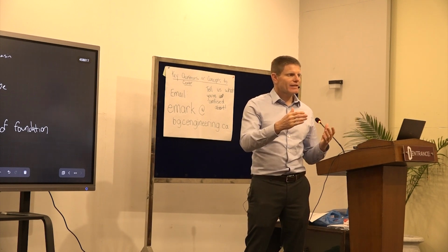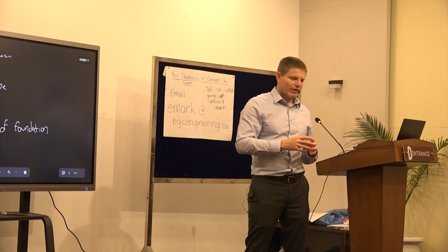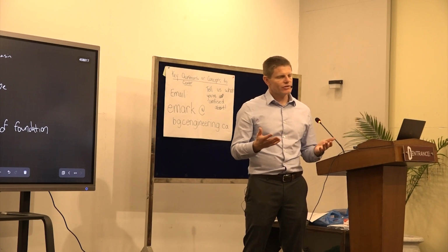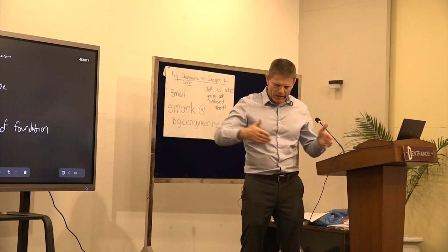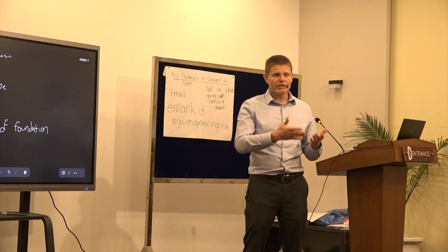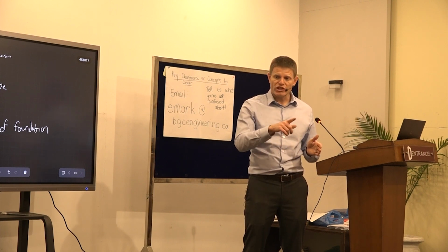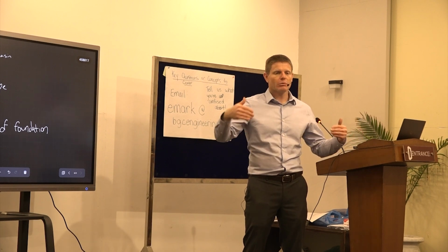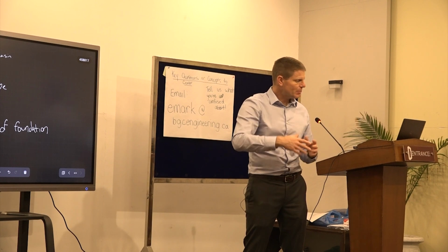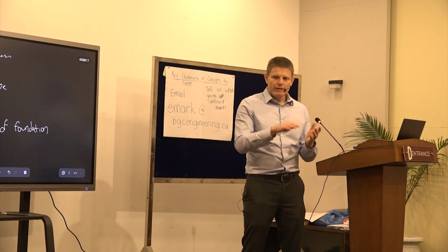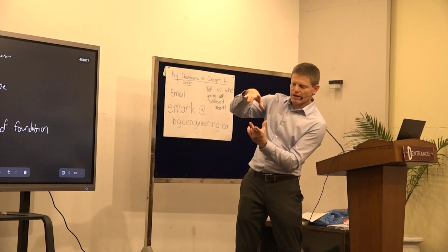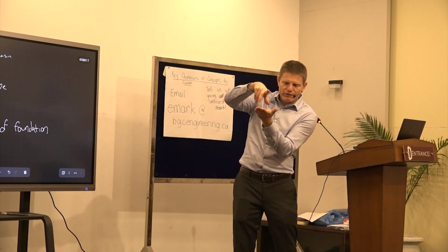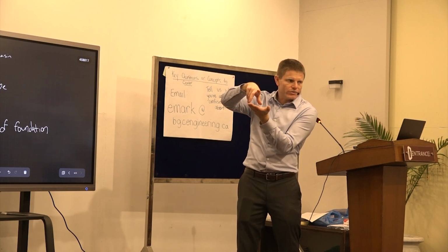And then the next thing is, it's important to understand the aggradation that would happen beneath a bridge, for example. So in some settings, you are in a steep and narrow section of the river, and during a debris flow or a debris flood, you will have erosion. But in other areas where the river is flatter and wider, that's where we have deposition. And when we have deposition, even if you had a sufficient opening initially for all of the discharge to pass, if you have deposition during the event, it makes the opening smaller, of course, right?